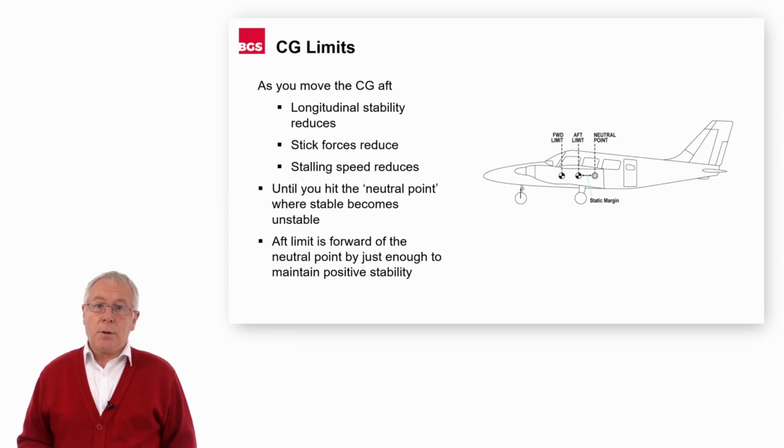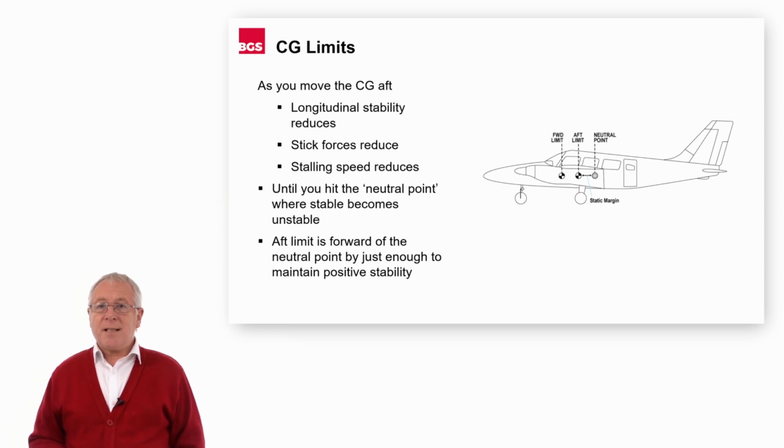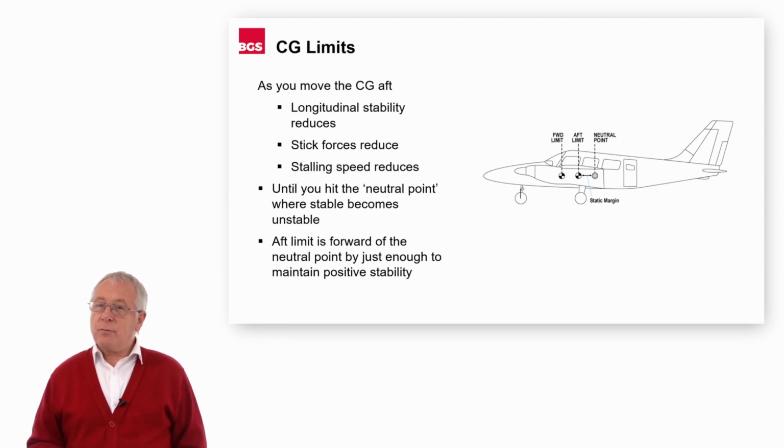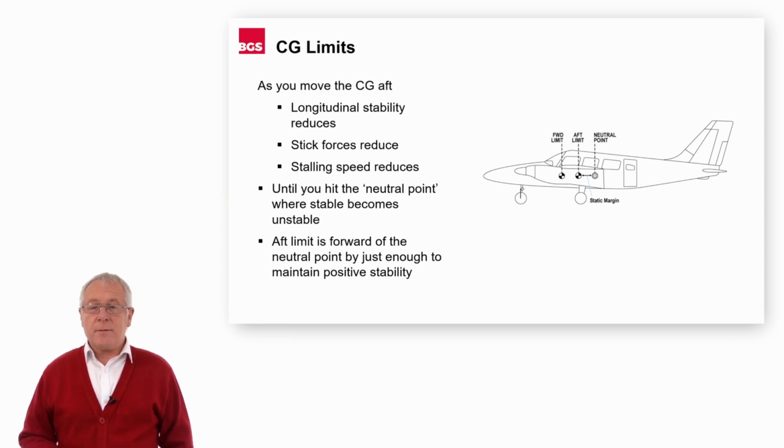It might interest you to know that on an Airbus A320, which is about 38 metres long, the centre of gravity movement during flight or at any time is limited to less than just 2 metres. It doesn't sound much, but also if just 2 passengers from the front of the airplane move to the back, the centre of gravity would change by over 5 centimetres.